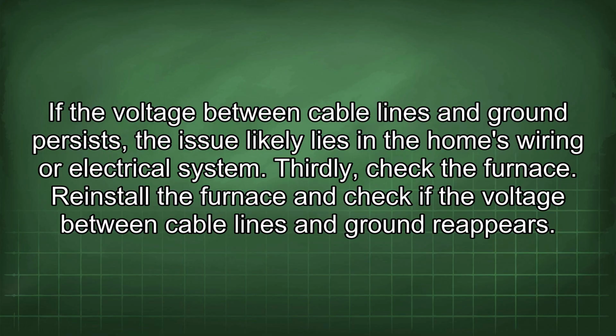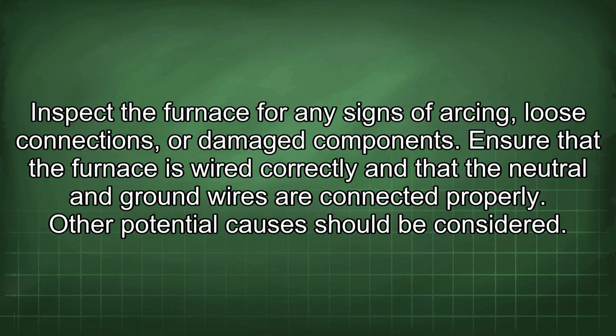Thirdly, check the furnace. Reinstall the furnace and check if the voltage between cable lines and ground reappears. Inspect the furnace for any signs of arcing, loose connections, or damaged components. Ensure that the furnace is wired correctly and that the neutral and ground wires are connected properly.